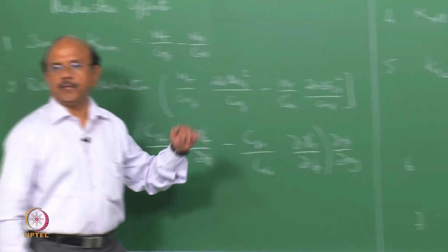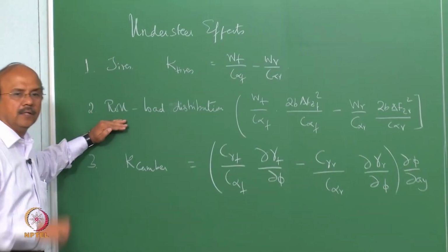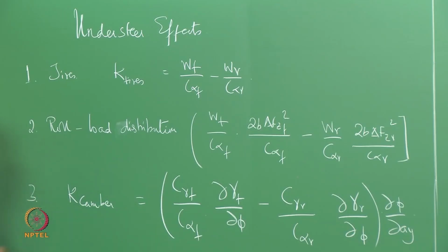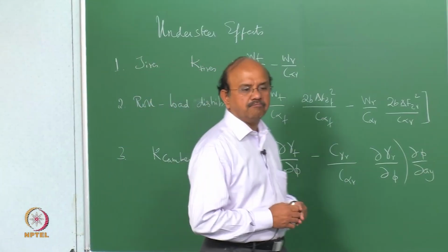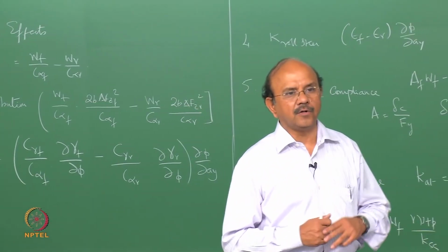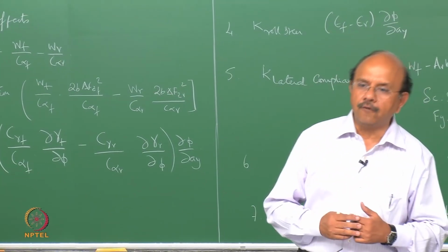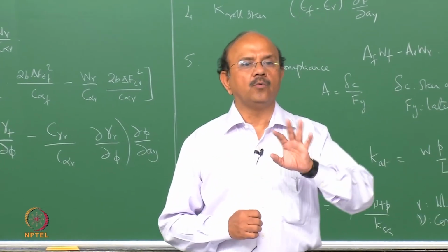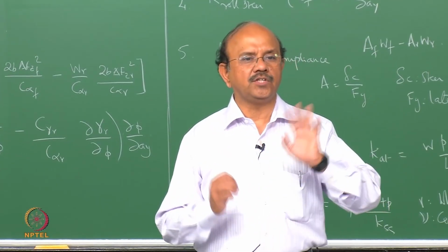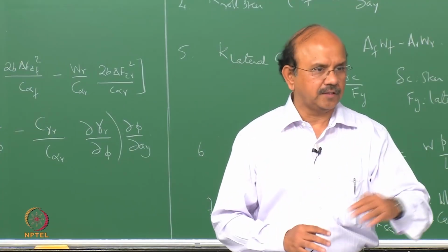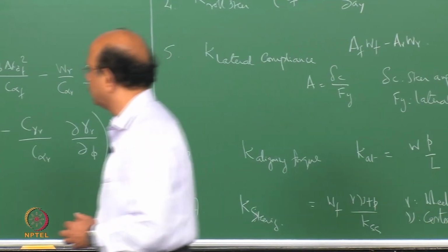The first thing, remember, we talked about the load distribution, redistribution during roll. We found that the nonlinearity with respect to FZ of the tire is going to cause a change in the alpha, in other words the slip angle front and rear, and so that roll would essentially cause a change in the understeer oversteer characteristics of the car. This is the first thing we saw. We saw that with the derivation.